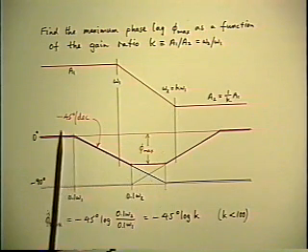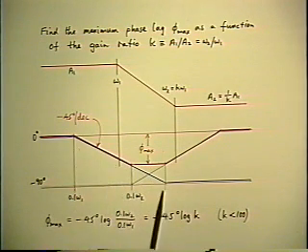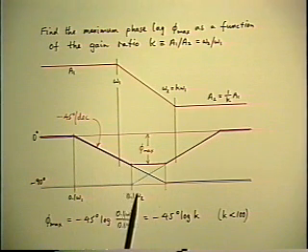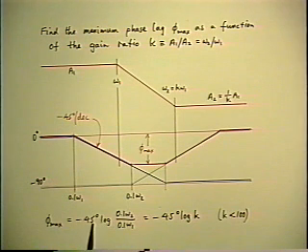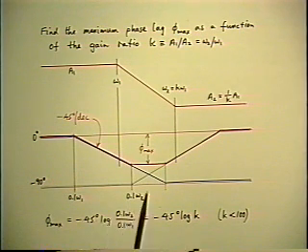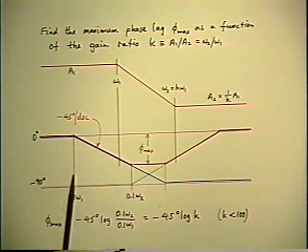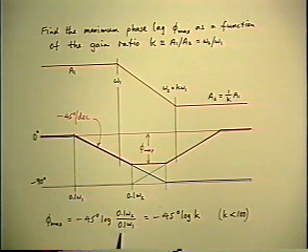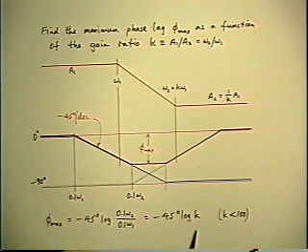So remembering that this is a semi-log scale, minus 45 degrees per decade of frequency, evaluating the phase lag at the frequency 0.1 omega 2 is simply the slope, minus 45 degrees, times the log of the ratio of 1/10 of the zero to 1/10 of the pole. The 0.1s cancel out, and the ratio of the corner frequencies is the parameter k, which is the same as the gain ratio that we're trying to throw away.